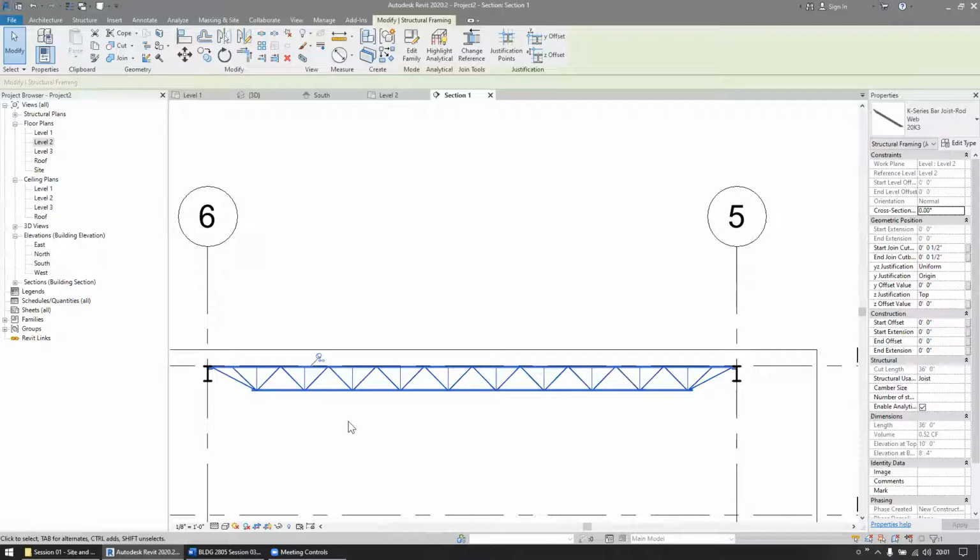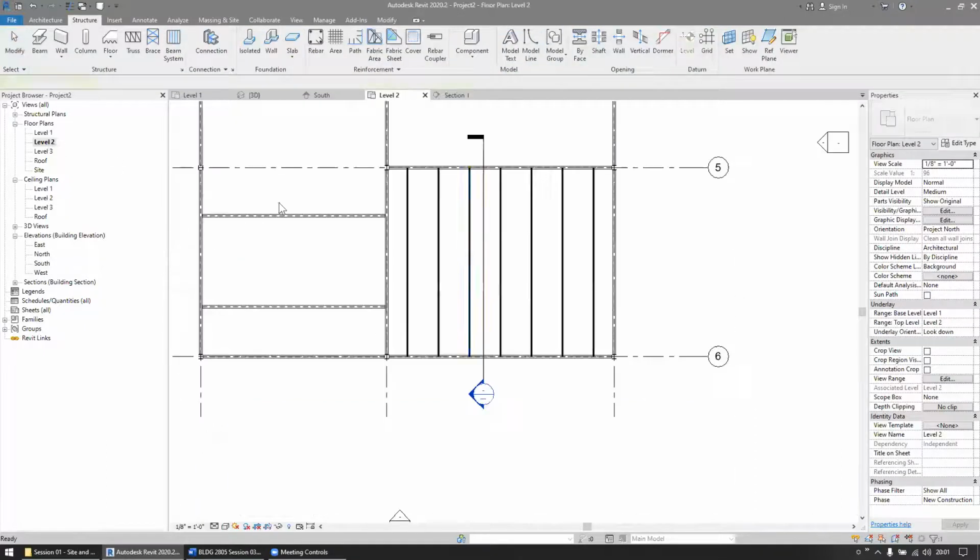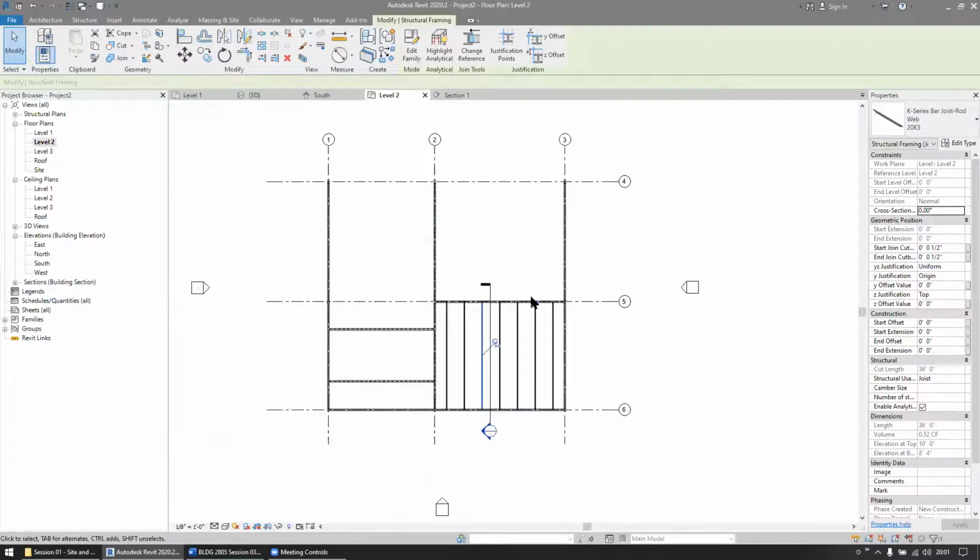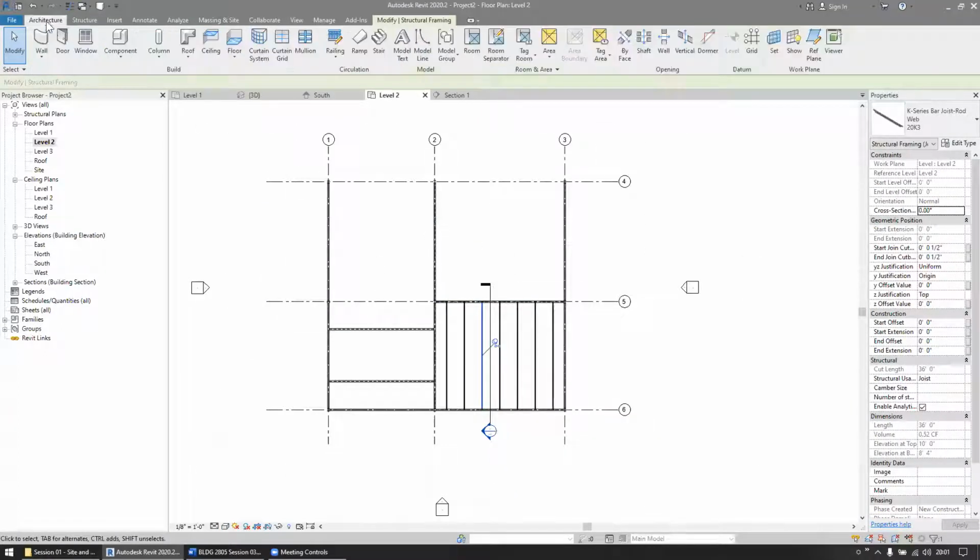So you got a 1.5 inch undulating steel decking, and then 2.5 inches clear concrete on top of that. So at the bottom of the flute, there's 4 inches of concrete. At the top of the flute, there's 2.5 inches of concrete. So that's pretty typical in the Vancouver area. So yeah, we can start putting in the structure, but let me just model this floor here.